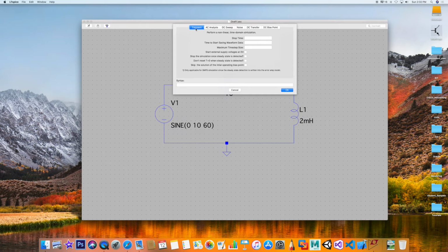Or 2. So, at this stage, let's say you didn't do the math. What is 60 hertz, right? What is that, 16.7 millisecond in terms of period? Well, we're going to have to prove that and see, indeed, if that's what we're going to be seeing, right? That's the nice thing about doing lab work. You get to prove some of the theory or the math that you use to analyze your circuits with.